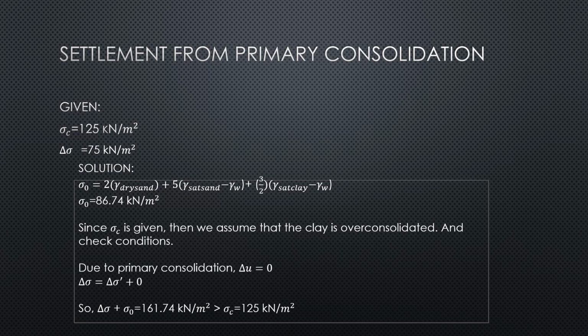So by adding the average effective stress plus the total effective stress, the answer is 161.74. Okay? So it is greater than the pre-consolidated stress. So it did not pass the first condition of overconsolidated clay.